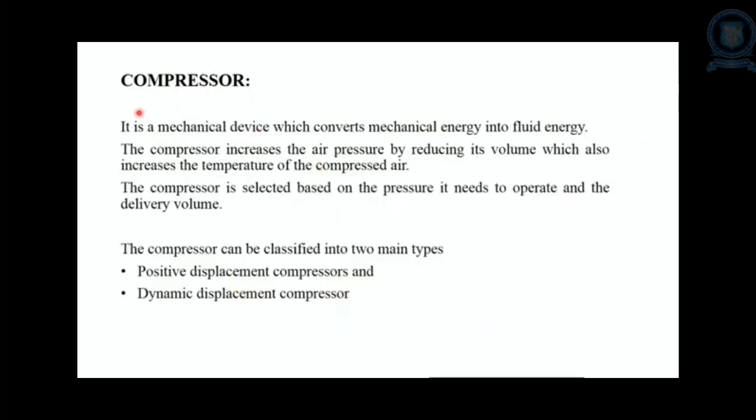Then compressor. It is a mechanical device which converts mechanical energy into fluid energy. The compressor increases the air pressure by reducing its volume, which also increases the temperature of the compressed air. The compressor is selected based on the pressure it needs to operate and the delivery volume.